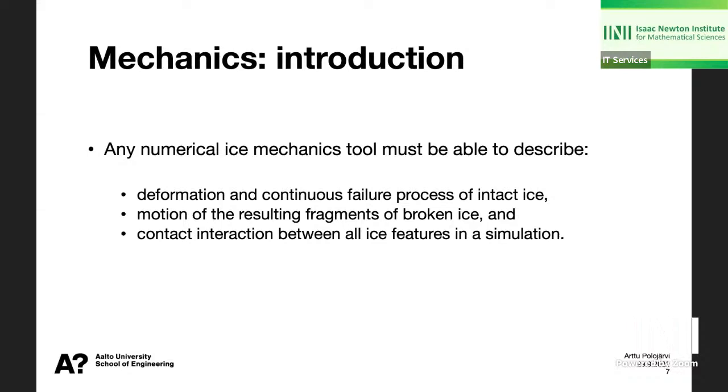What you have to be able to do is to describe deformation and continuous failure process of an intact ice sheet. I would say the key word here is continuous failure process. It's not enough to just model ice sheet fracture once, but you have to be able to run several situations where the ice sheet fractures in a simulation. You must then be able to model the motion of the ice fragments that come out from these failure processes, because otherwise you won't be having any ice pile-ups or any ridging or anything like that.